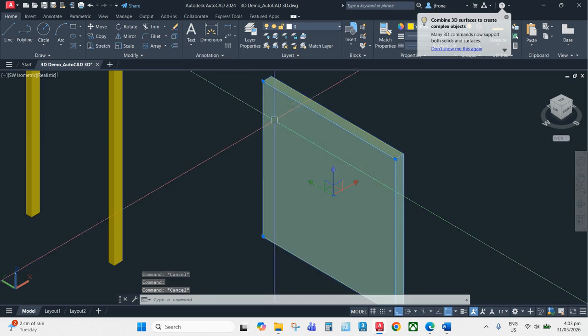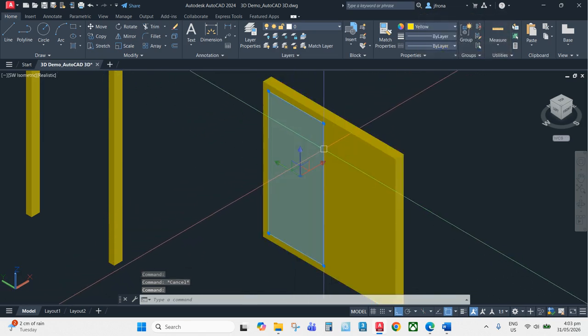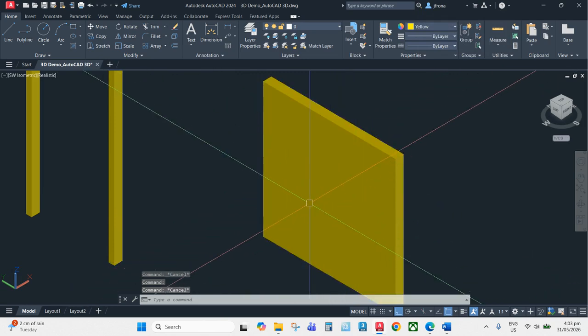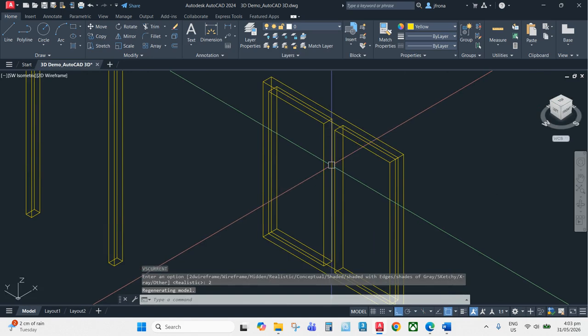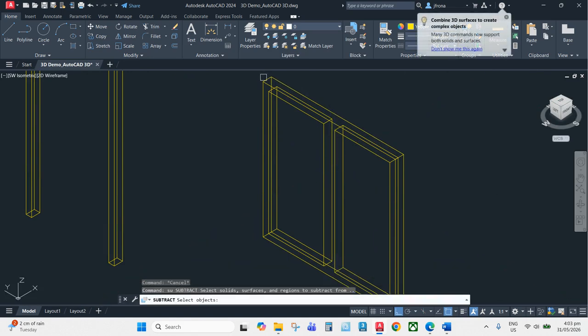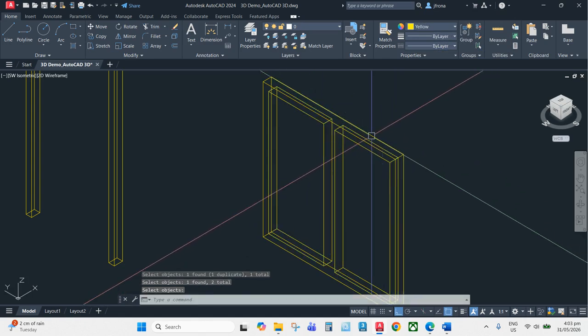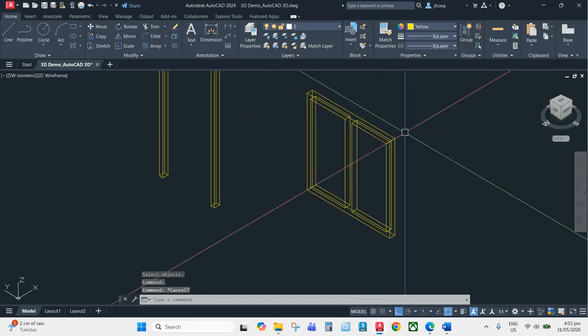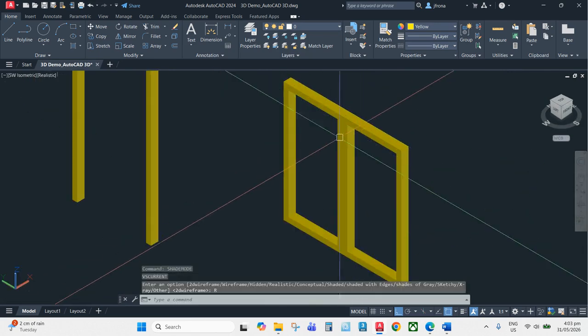the insides. If you can't select them, it's probably because you cannot see the line. So if you want to go back to the 2D wireframe from your shade mode, you can do that so that you can select the interior objects, the objects that are inside this big volume or the rectangle. And if you go back to shade mode, the realistic, you already have your voids.